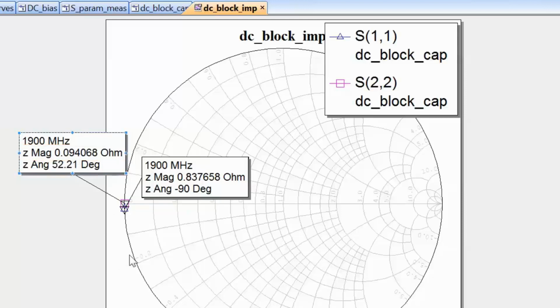And that is because, of course, whereas an ideal capacitor cannot go over in terms of the value of its impedance to the other side of the chart, a real capacitor, which has got some inductance associated with it, has got this extra push due to the value of the inductance at a specific frequency, which can take it up to the inductive part of the Smith chart.